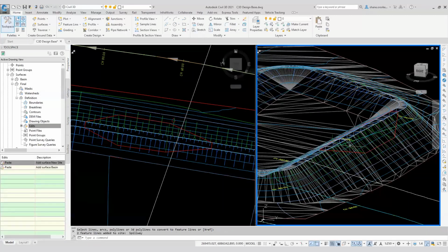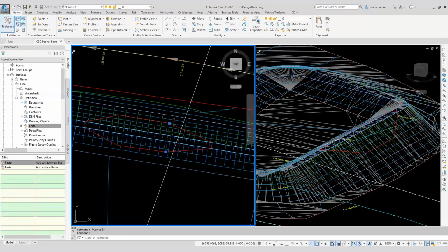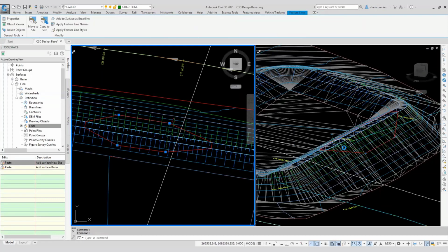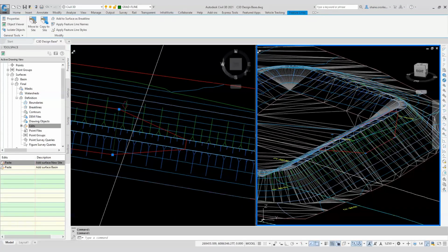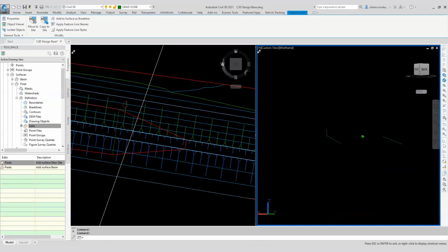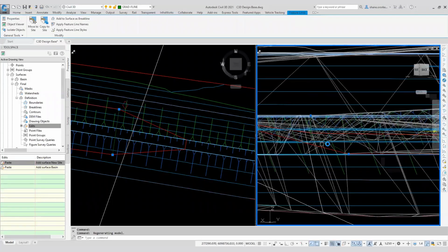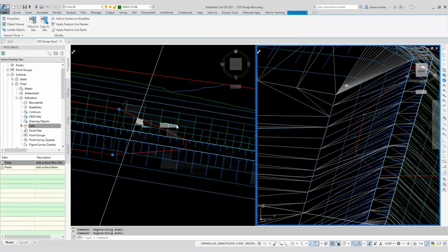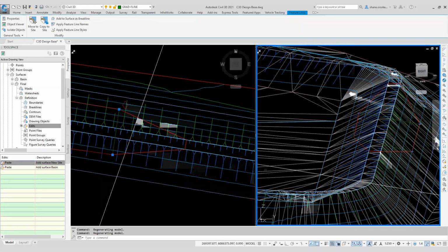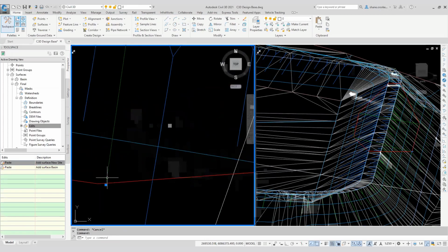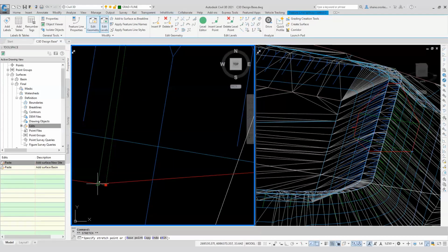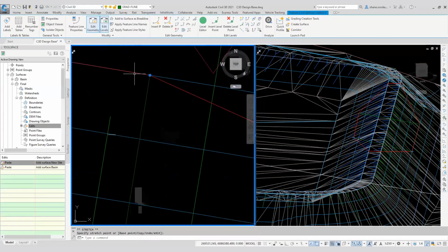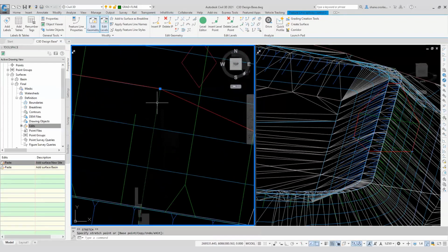But what you'll see when we look at these features, when I click on them, if you have a look in 3D, you see those green lines. If I spin this around a bit, they're actually tapping onto the red. Now I can see here I've got a problem where this doesn't, because I didn't get my snaps right. So let me just fix up my snaps. Really lazy. You can see I don't use CAD enough. But I'm snapped at the other ends.